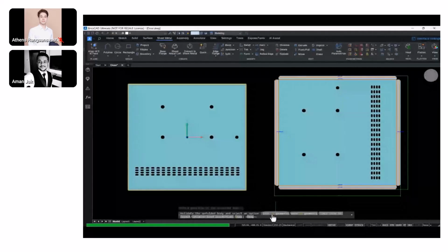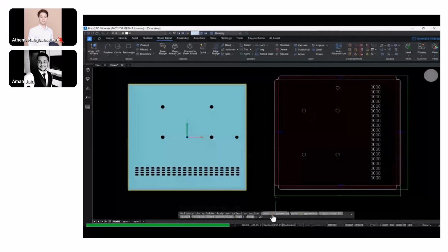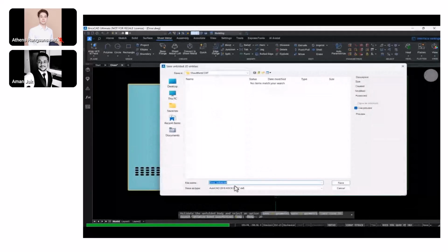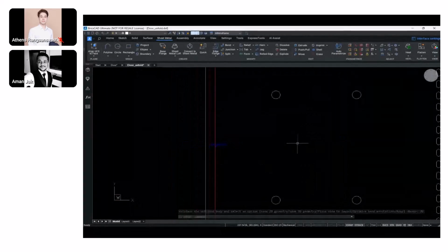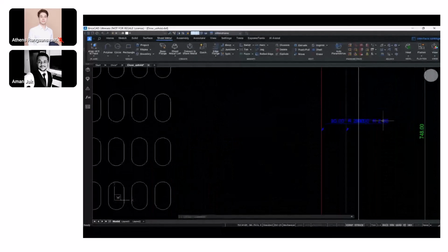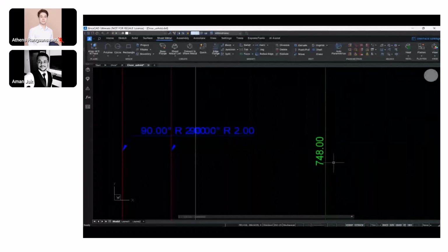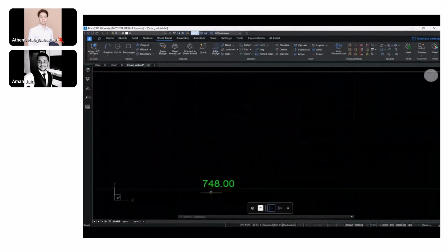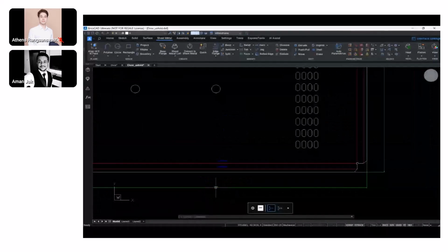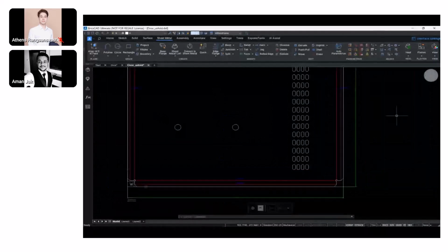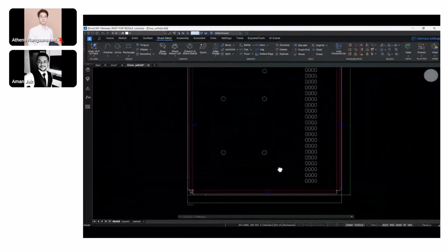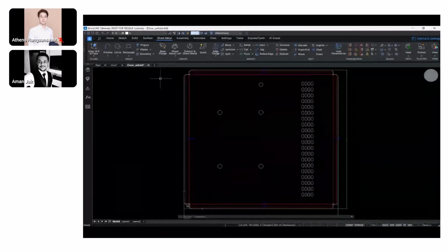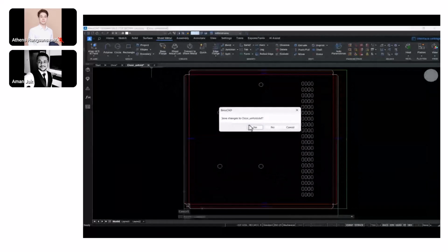And I can save this 2D geometry as a DXF file. So it's kind of a one-click DXF. As we looked at in the process, where we need an input from the CAD software to the machining software, this is the one that's most widely used. It can be used in most CAM software worldwide, and then the machining codes can be generated on top of this. As you can see, the bend lines, the representations, and the reliefs have automatically been created for the DXFs that we have in place. Let's save this.